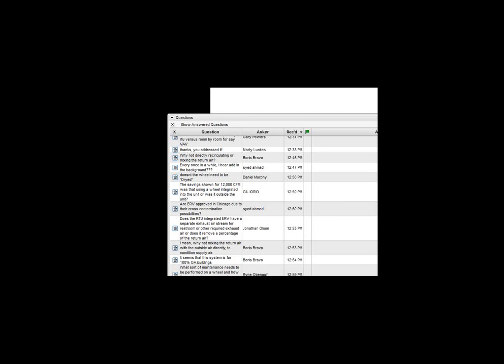But that EATR is a tested and published number. The City of Chicago requires 0. So if you have AHRI certified data saying that you have 0 EATR, you can use it in the city of Chicago. By the way, the city wants 0.0. 0.1 doesn't count for the city. I've learned that the hard way. It's got to be 0.0. I've done it with wheels, and I can certainly do it with fixed cores. Fixed cores are always 0. They're guaranteed, right? But a wheel you can do by putting the fans in a certain position. And I've got a whole separate 2-hour webinar on ERVs that I could send you guys a link to if you want to see how to do that specifically.